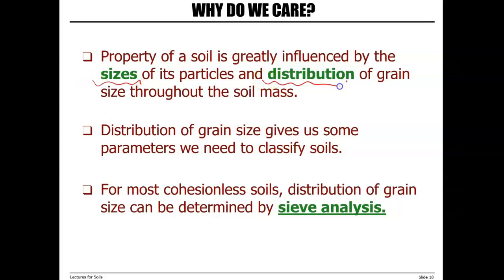So, size of particles, if we have coarse particles, or if we have fine particles, or if we have a combination of fine and coarse and medium size particles. So size and percentage of different particle size, or distribution of grain size. These are both important because both of these will have an effect on engineering properties of soil.